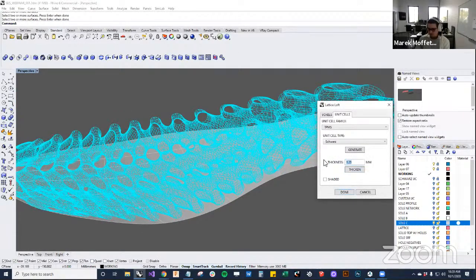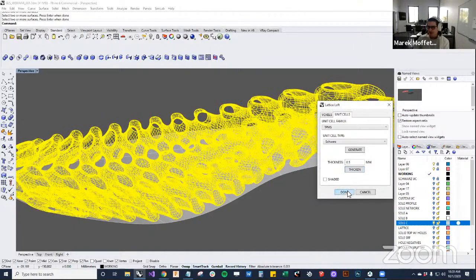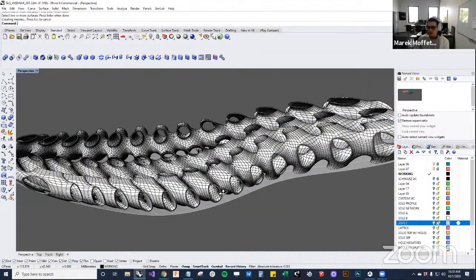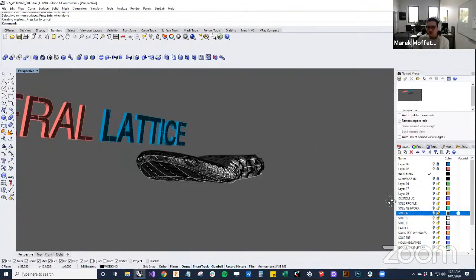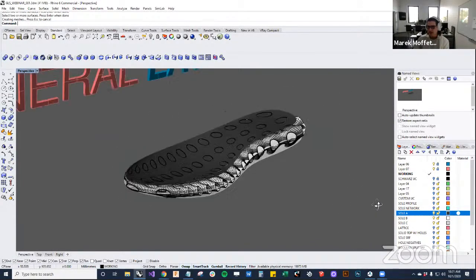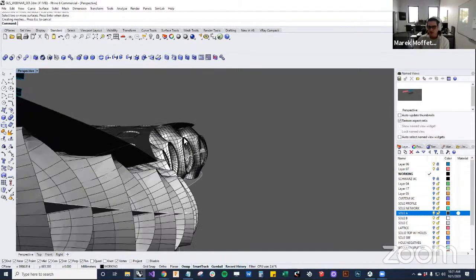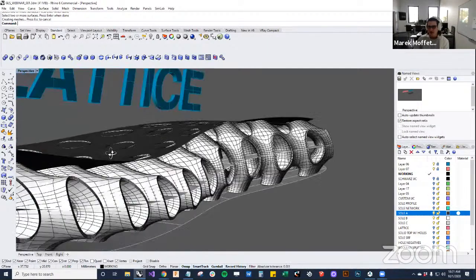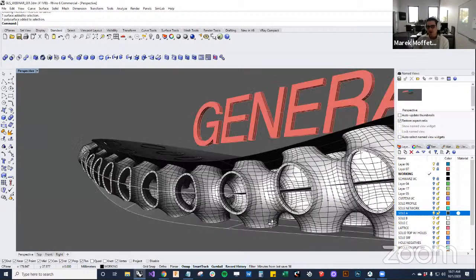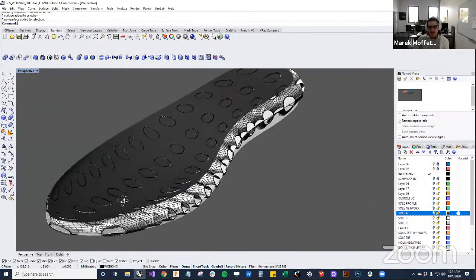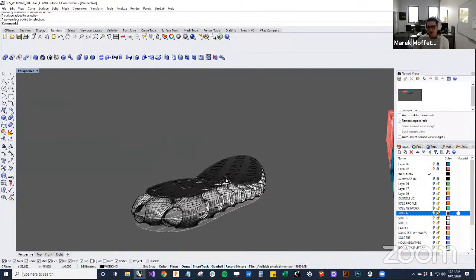Great. And so we'll thicken at 0.5 mil. We'll hit done. Awesome. So now we have a structure that is conformal through these surfaces. In using this third middle surface, we get the curvature around the side. It's except, just the surface to surface, which it would be planar all the way around the edges, and aesthetically not terribly pleasing for a midsole.